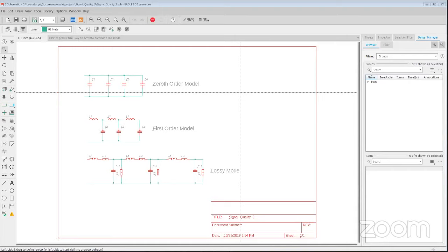And in those 4 seconds, if you were to hold the battery and you had a meter there, you would actually be able to measure current flowing through that until the whole round trip has completed and all these capacitors in that transmission line have filled up, and then you would read open, assuming that you didn't have anything connected on the other end. So what you're looking at here is the behavior on nanosecond timescale.